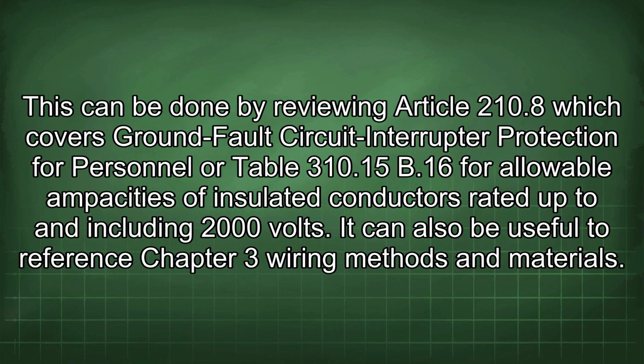This can be done by reviewing Article 210.8, which covers ground fault circuit interrupter protection for personnel, or Table 310.15(B)(16) for allowable ampacities of insulated conductors rated up to and including 2000 volts. It can also be useful to reference Chapter 3, wiring methods and materials.